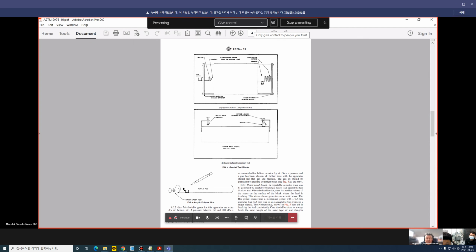Okay. So in this situation, you have the best conditions. You have a smooth surface where you have your sensor mounted. You have a good coupling with high vacuum silicon grease. And you perform the pencil break 5 centimeters away from the sensor. So you take note of the amplitude 3 times. All right? And you calculate the average.